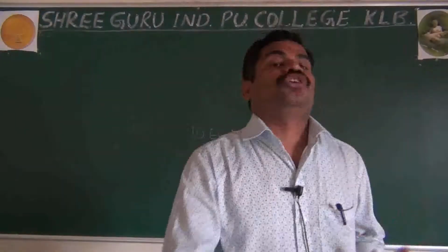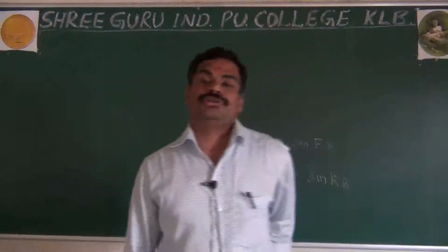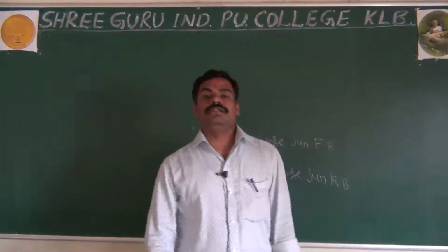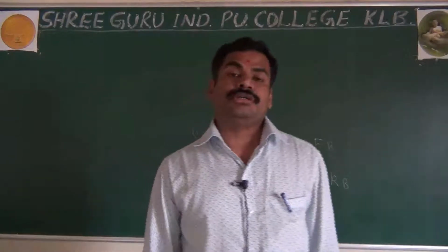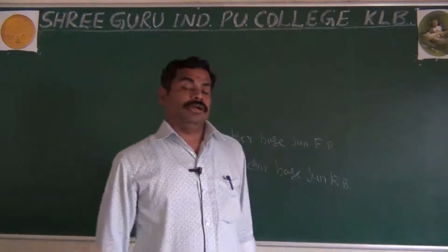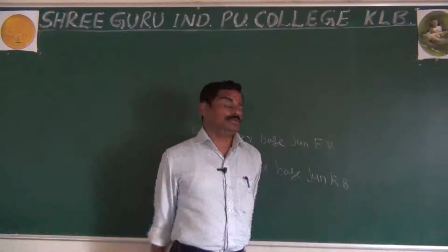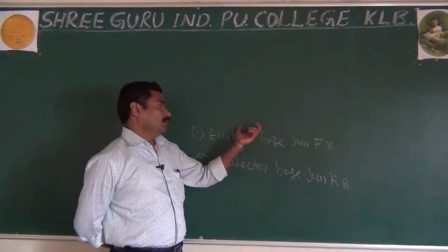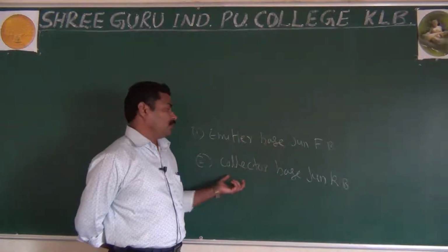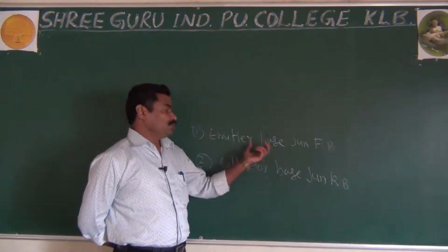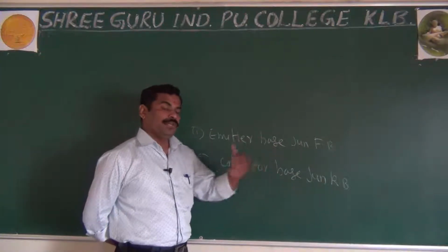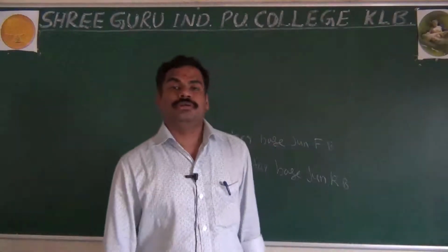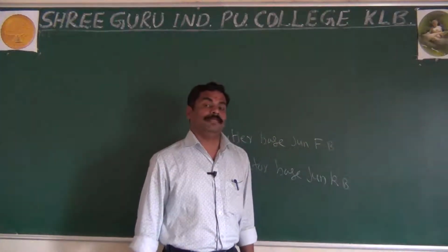Because you are studying this topic about transistor amplifiers, it means how we can use the transistor as an amplifier, as you have studied already. Only in the active region does your transistor act as an amplifier. And as we know already, what is the active region? In the active region, the emitter-base junction should be forward biased, and the collector-base junction should be reverse biased. If this condition is satisfied, then only your transistor acts as an amplifier. This is the normal condition of your amplifiers.